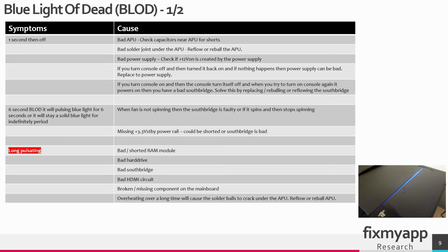Also check the 3.3 volt standby power rail. This could be shorted, or the Southbridge could be shorted or defect. So the 3.3 volt standby is one of those critical power rails.